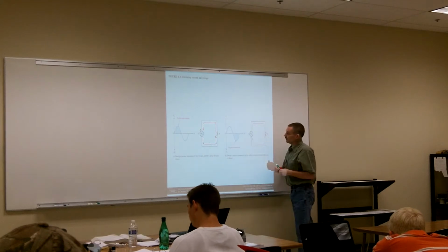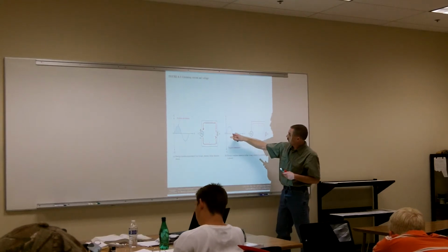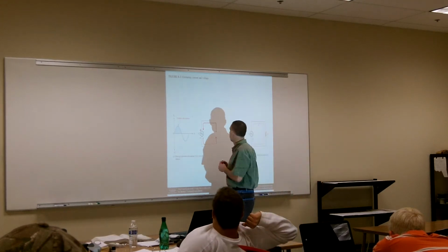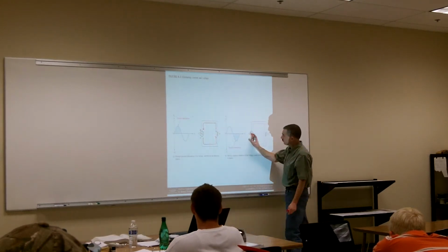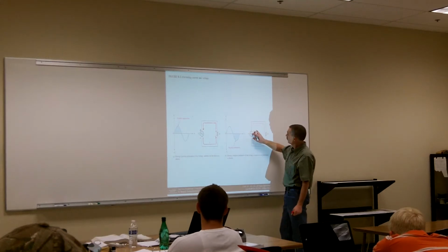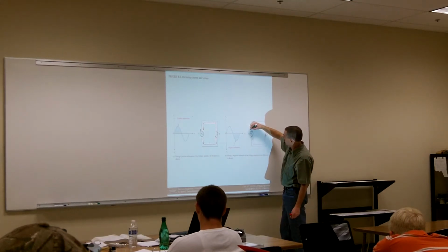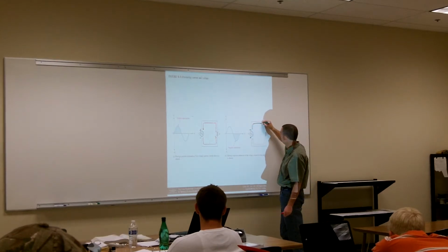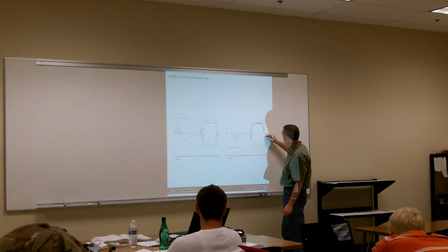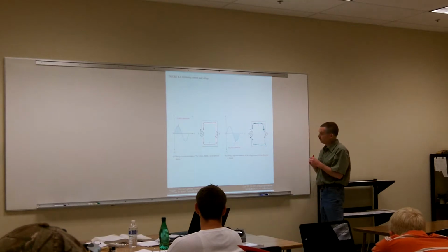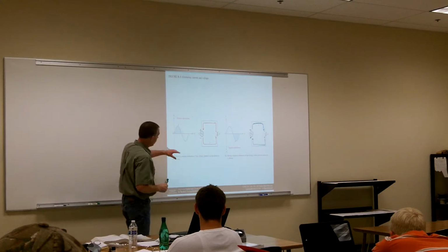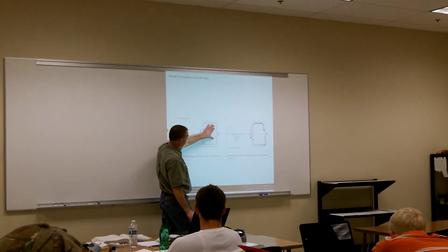Then on my second alternation, as it crosses zero and goes to my negative alternation, my polarity across my source is now going to change directions. That's going to go positive, negative, and this time my current is going to go this way. And put the polarity across the component, and then back up. So that voltage across the resistor is always going to be changing polarities.